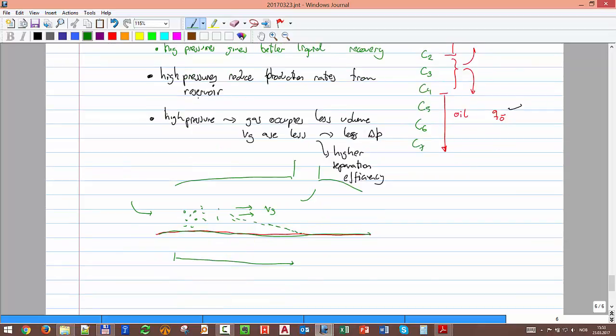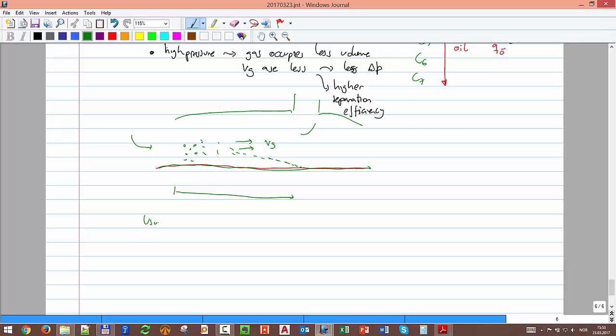So the conclusion of this discussion is that usually for oil, the pressure of the high pressure separator is 50 bar or less. Okay? And that's just because it's a liquid production and it's very much influenced by the pressure drop between reservoir and separator. If I can take it even lower, that's great. But I have to be careful with the amount of gas that I have. If I go down too much, for example to 30, 20 bar, then the gas will occupy a big space and then my separation efficiencies will be very bad.